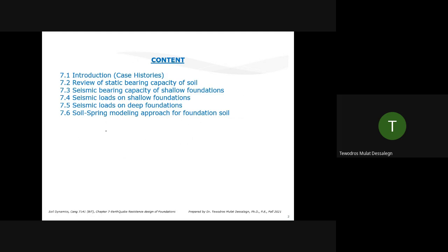Nowadays, the commercially available software like Plaxis and FLAC have limitations doing that. So what we usually do as geotechnical engineers is approximate the structure and fully model the geotechnical portion. The reverse is true for structural engineers. They approximate the soil with soil springs, and then they fully model the structure and analyze it. So we'll see those approaches.